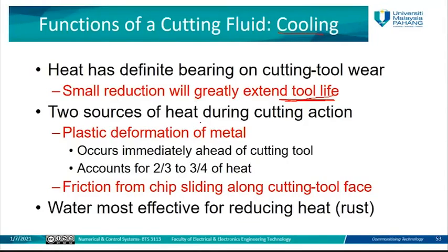There are two sources of heat during the cutting action here. From where does the temperature come? First, plastic deformation of metal, and second, friction from chips sliding along the cutting tool face. So this is the main reason for generating the high temperature during the cutting process in the CNC machines.